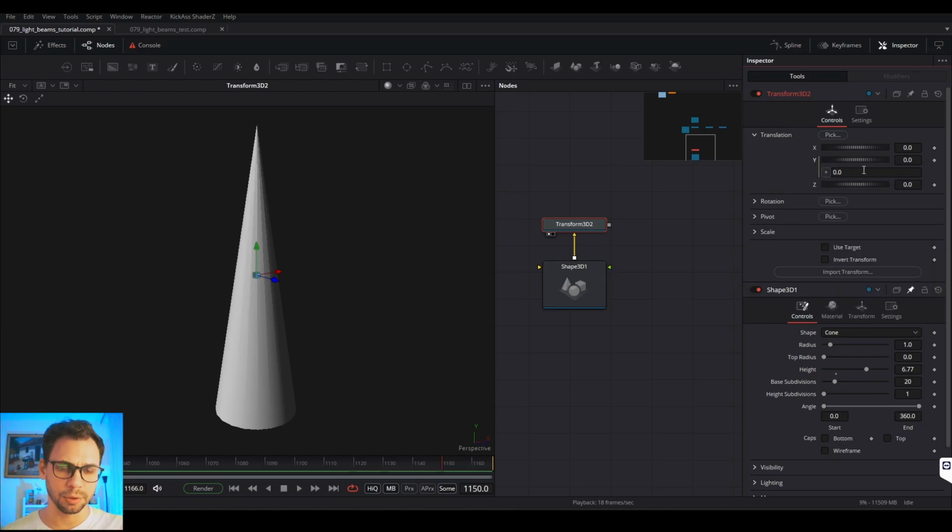In this field, you can type expressions or connect the parameters between each other with this plus sign. So I select it and drag it. So you hold the left mouse button and drag, and you can point to the parameter you want to link to. In my case, it's going to be height.